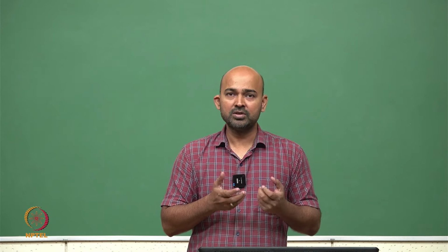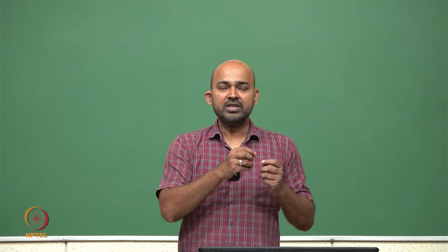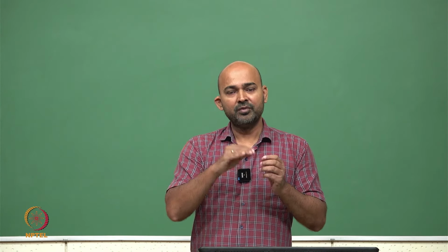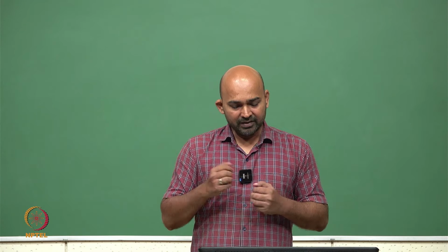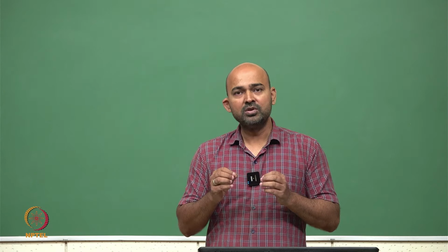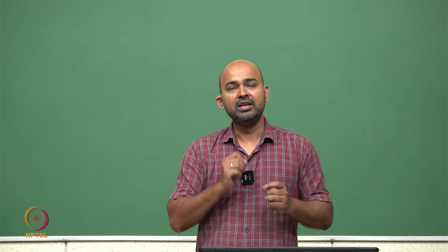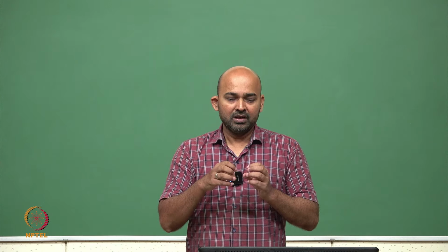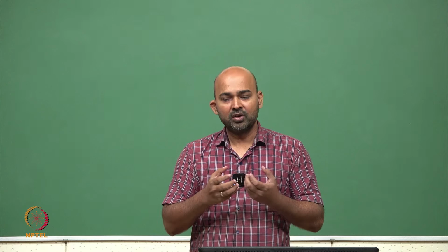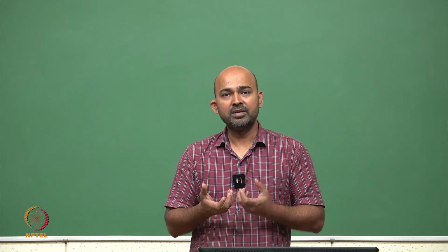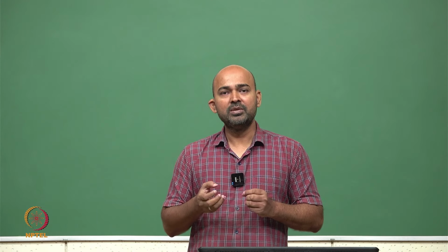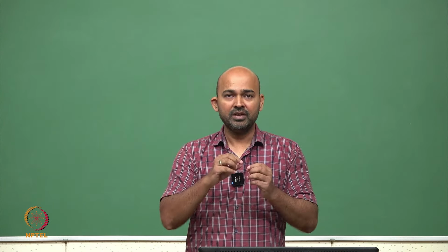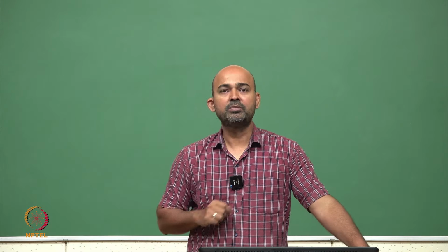We have 3 inputs and 1 output in that circuit. When we change the input parameters in digital form 0 1 0 1, we see the waveforms are changing based on the applied input, and then we saw that there are intermediate values or intermediate wires which we are interconnecting these gates. These can also be saved, and are very useful in cross verifying. If the circuit implemented has any problem, then these intermediate values are very important. We can go to individual gates and check the output whether it is giving the desired result. If not, then the problem is close to that particular wire.